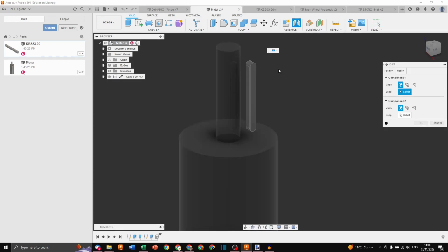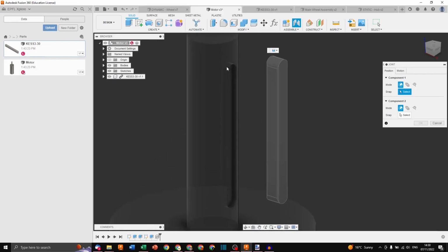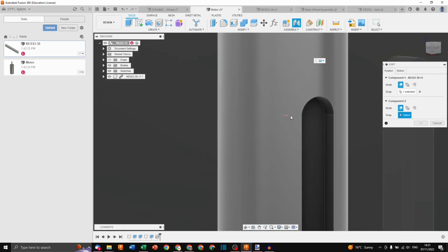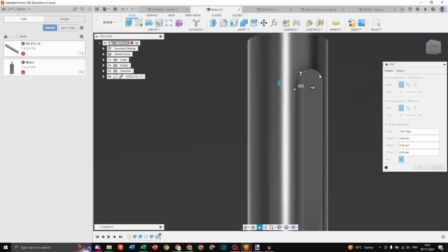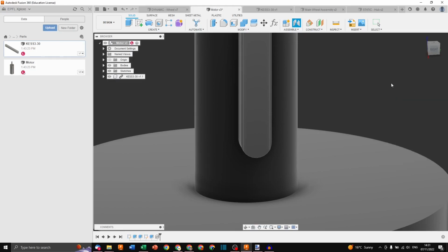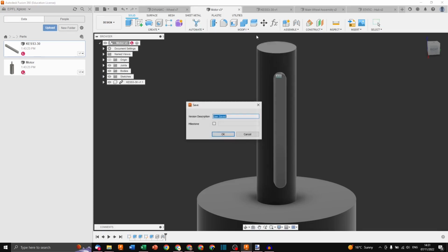Alright, so I'm now creating a new joint between this keyway and this motor. I'll do it straight into the motor file. For this, I click on new joint, and now select, for example, this half circle and this half circle. And now in theory, my keyway should be perfectly set into my part. Motion, rigid, okay, perfect. New keyway, inserted into design, new joint. Great.